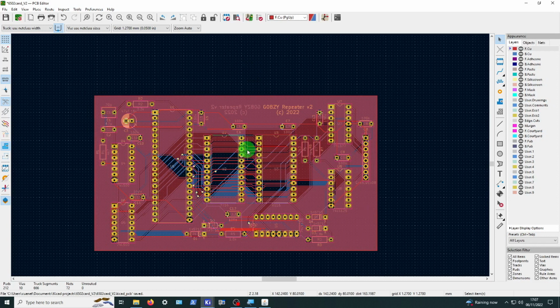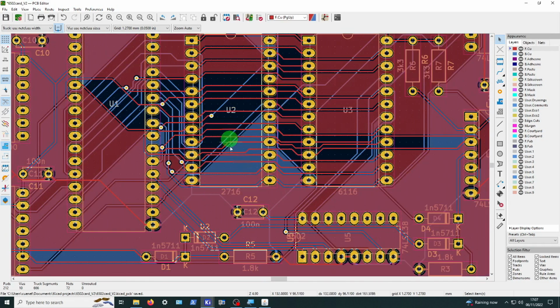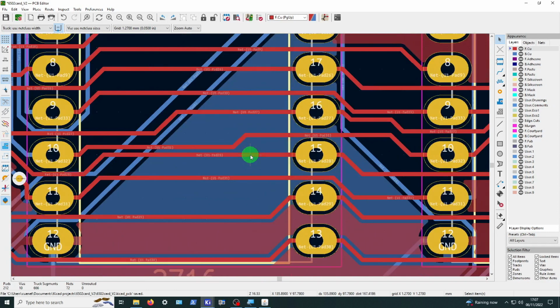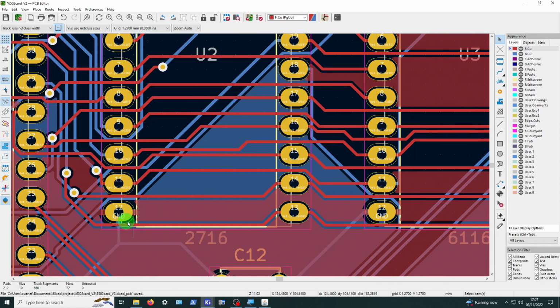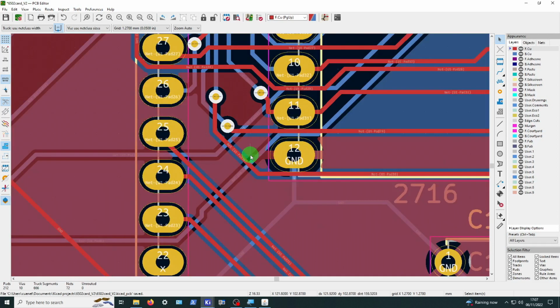So far so good. There have been occasions when I've done boards like this and the top copper wasn't connected through to the bottom copper in certain areas, like round here. Like if this was, say, a ground, and this area here wasn't actually connected to ground. This little bit of copper here is not connected to anything, it just goes to this pin.